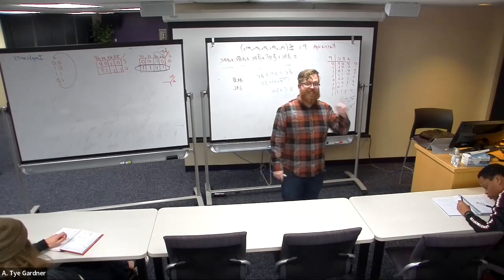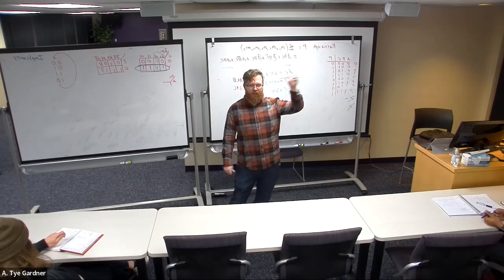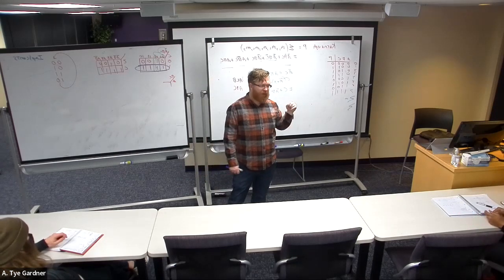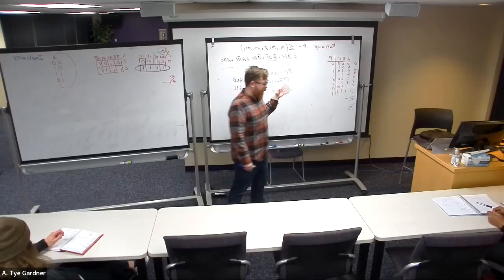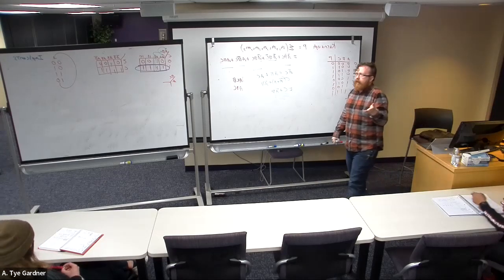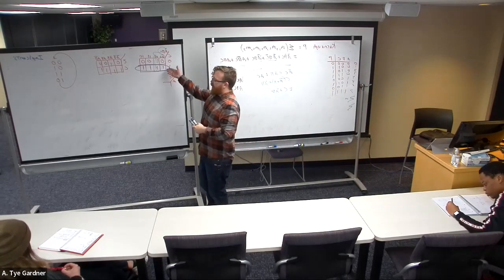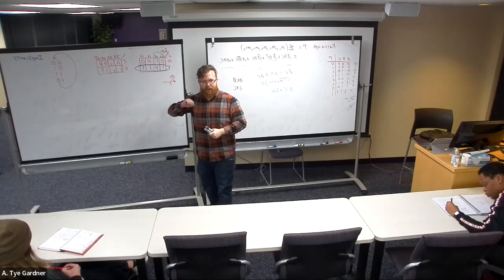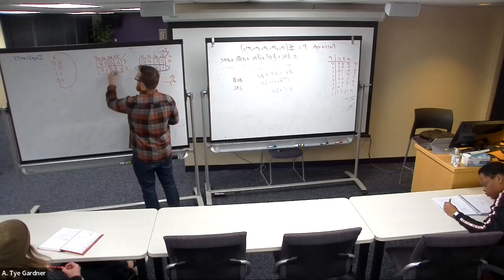Anyways, that's the essential prime implicant. The most important word to know is implicant, and the second most important thing to know is essential prime implicant, and the regular prime implicants, just throw them away, I don't really care. Essential prime implicant is basically saying that I drew this picture in as few circles as possible. Because it is also valid to do these two and those two and those two.